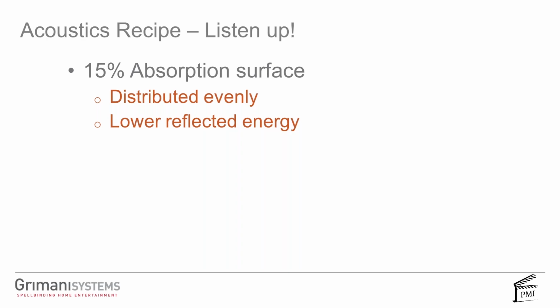If you actually do more than 15% absorption, the room's going to start to be too dead. And like Jason said, it just doesn't sound good. It sounds bad. I've been saying about 20% of the time that you shouldn't put more than 15% absorption surface. So you want to lower the reflected energy by about 15.